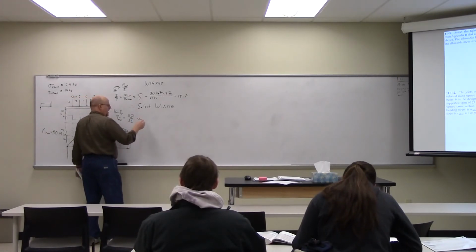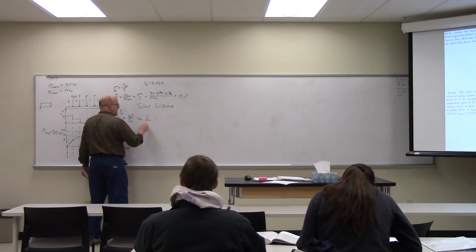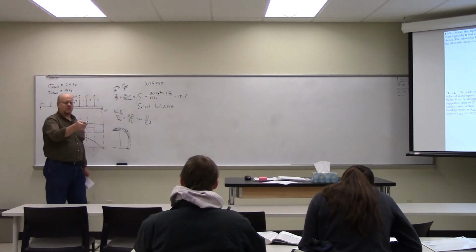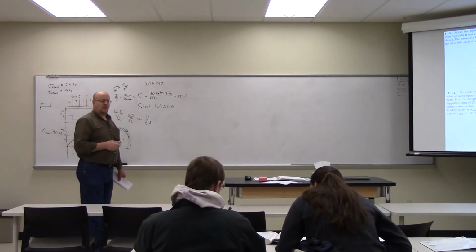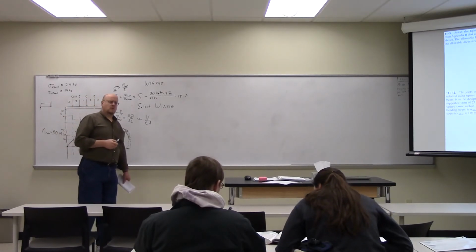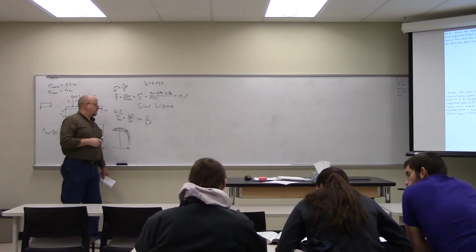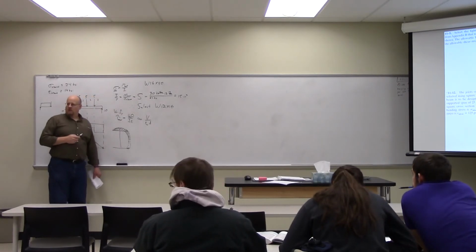that is often allowed where we just care about V over the thickness of the web times D, the height of the web. I think it's D, the D that they use in the book, the height of the web. D, yeah, top to... look at the picture, is that the top to bottom dimension of the I-beam? Yeah. You see what I'm saying?